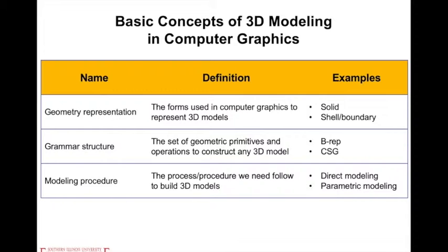The solid model is usually used for analysis, to analyze not only the boundary shape of the object, but also the interior material structures, like stress, strain, and some cracks. So for this one you need to use a solid to model the structural columns or beams, and then to do the 3D analysis.